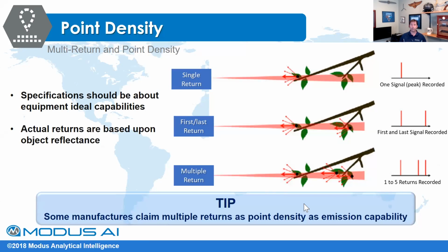It depends on, again, that application that you're going to be doing, whether you just need the top layer, which is a digital surface map. If you need to do a DEM, which is a digital elevation map, where you want to pull the surface off and just see the bare earth readings. Or if you really want to get into canopy and feature, you get multiple returns. So if you remember the first example I showed with the Riegl and the Velodyne, part of what you were seeing in that model, in addition to resolution, was you were getting more returns. And therefore you were seeing more under the canopy in the Riegl. And again, it really depends on the application that you're going to be doing.